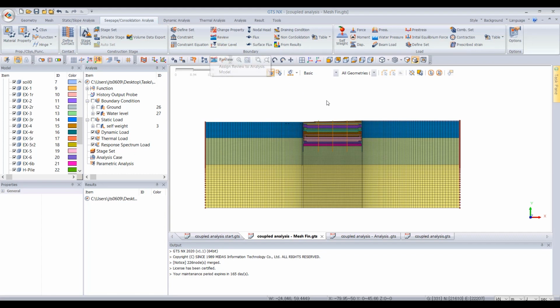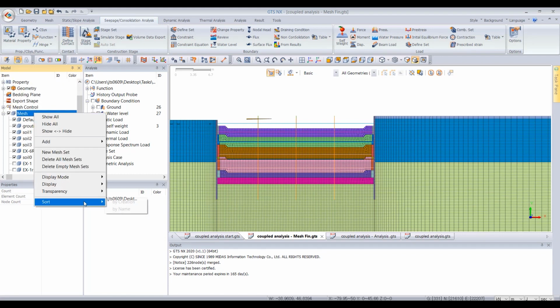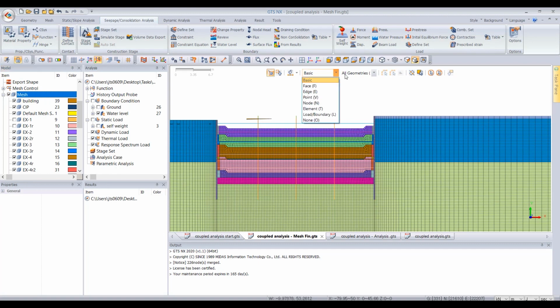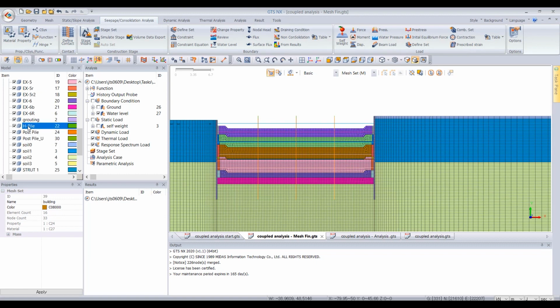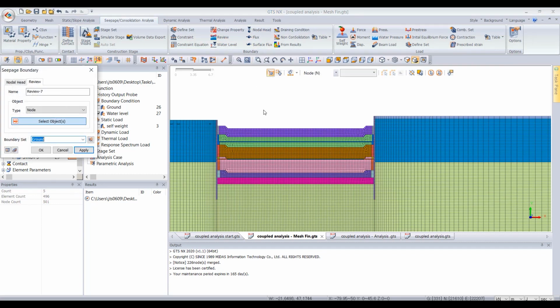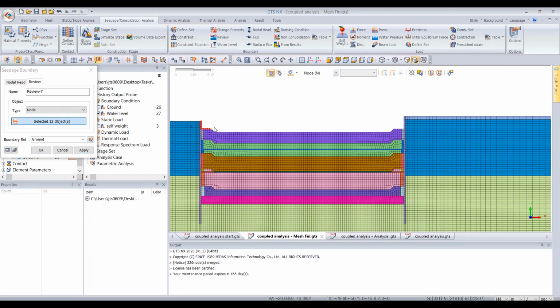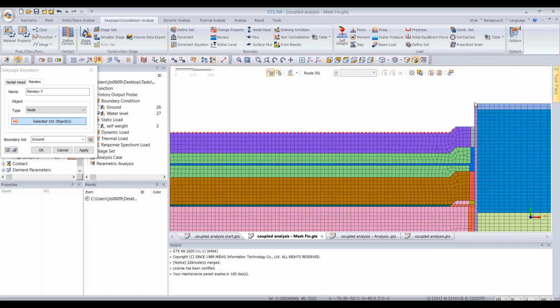And also I have to assign the limit boundary for every excavation part. So I will hide the first excavation parts, without the H piles or post piles and struts as well. Go to the review boundary over here and click here to see the water flow and water quantity during the excavation.